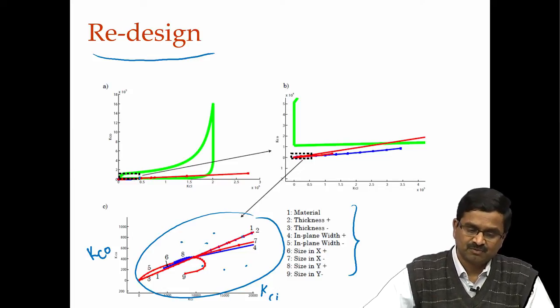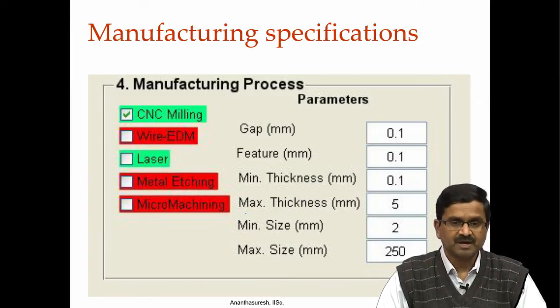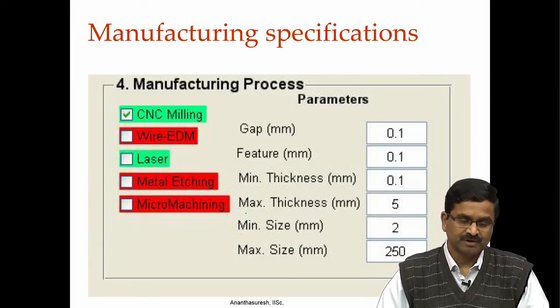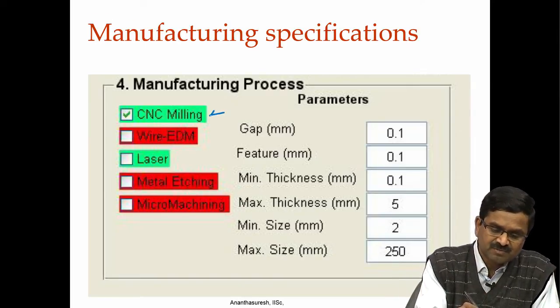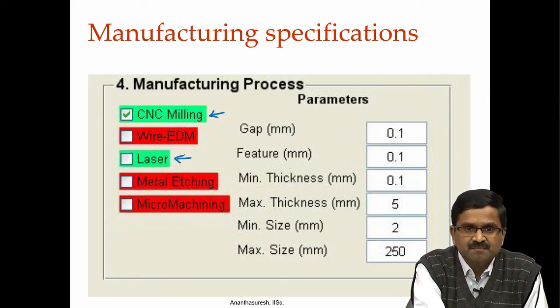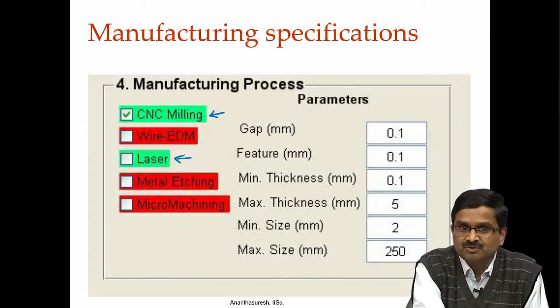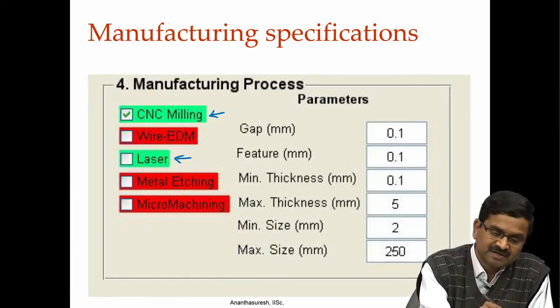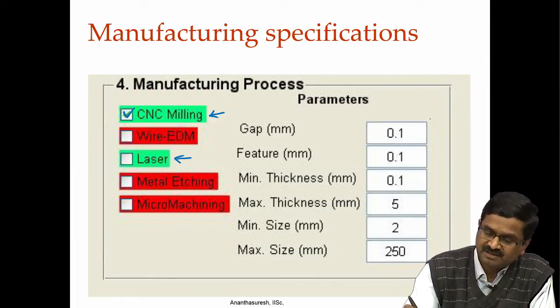Okay. So, until it is satisfied you keep on changing. When you do so, in the window it also shows for any mechanism that you have chosen in green which are possible processes. In this case laser micromachining and CNC milling are applicable, whatever people who stored the mechanism in the database know with what manufacturing processes that mechanism can be made. We indicate that in this particular case CNC milling is chosen, and there you can enter in millimeters.